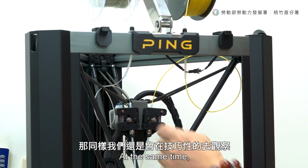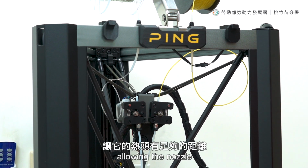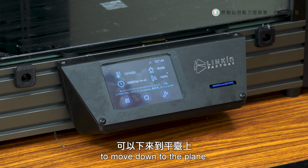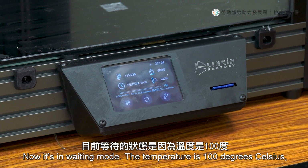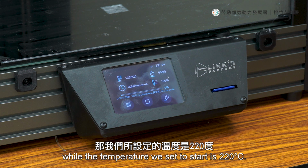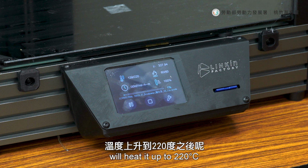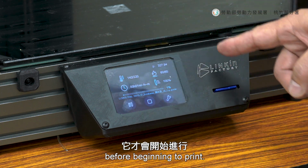At the same time, we need to observe if the filament is extended to proper length, allowing the nozzle to move down to the plane. Now it's waiting. The temperature is 100 degrees Celsius, while the temperature we set to start is 220 degrees Celsius. So the system will heat it up to 220 degrees before beginning to print.